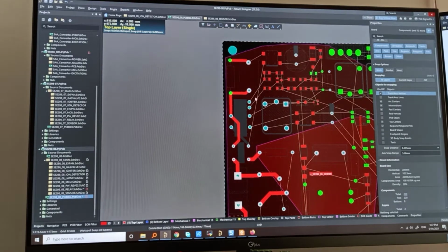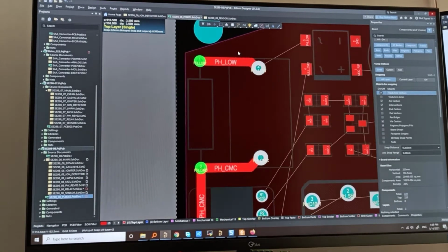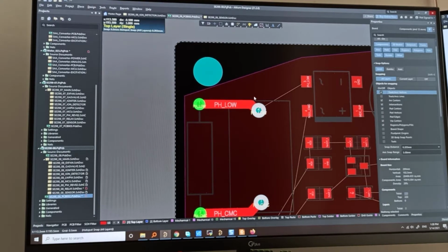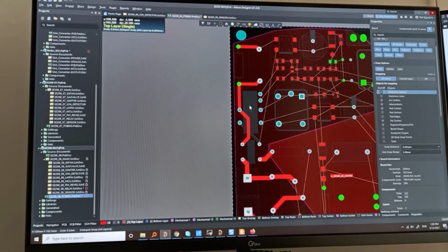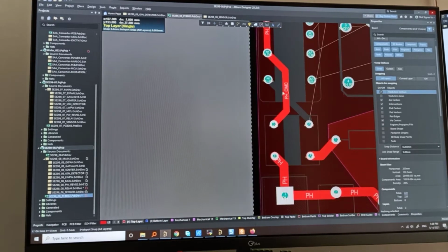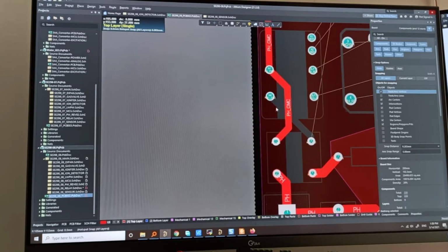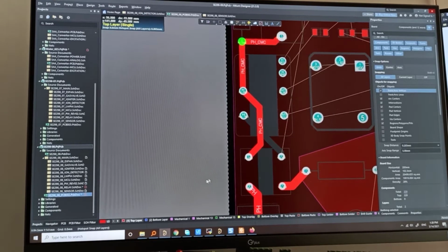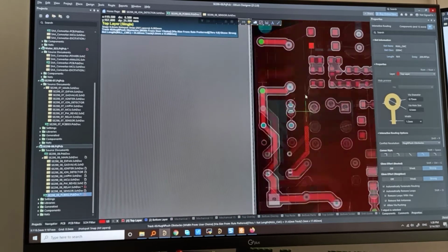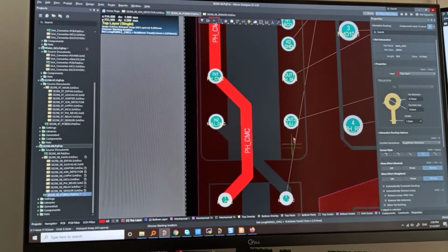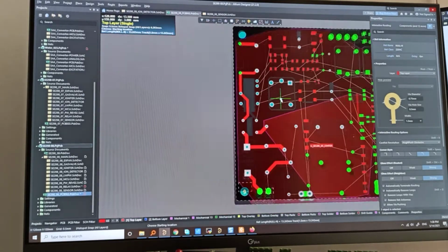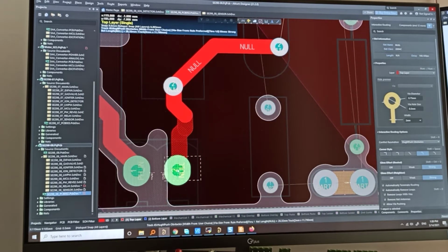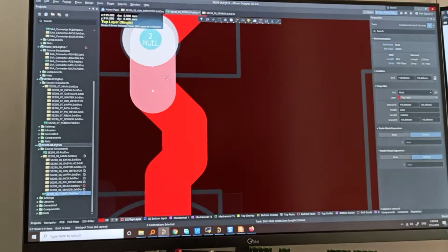As you can see, I try to use the top layer because we want to use the bottom layer as a shield everywhere it's possible, and I hope it's the main node, the circuit main node.